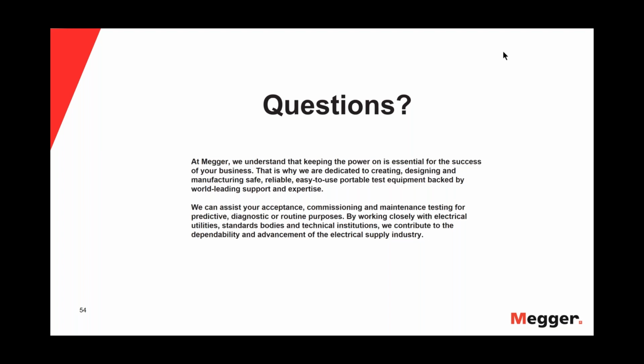So the right way to set it, you don't set your thumper up for the coincidence method. You set your thumper up for the fault that you're working. And once you've done that, the coincidence method is going to fall right into place for you.